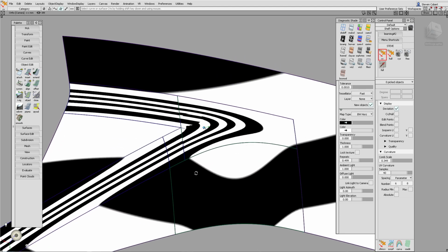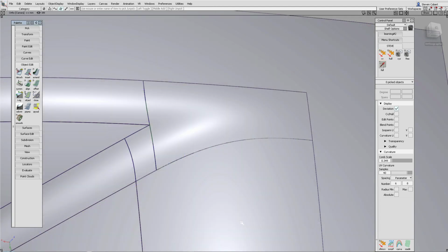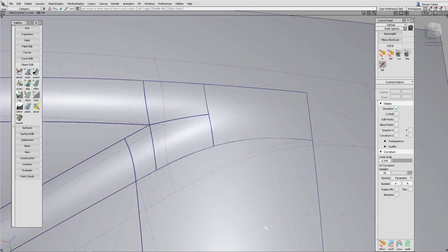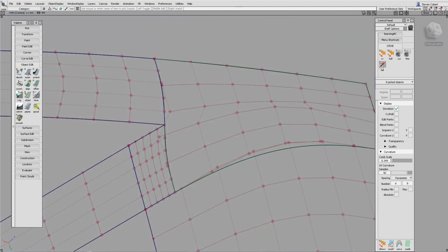The final stage is to split up the surfaces and align them. We need to divide the surface into 3. Where we divide them is a matter of judgment. We don't want the first divide to be too close to the fillet ends, otherwise there's a risk of wobbly surfaces when we come to align them. For now I'm just going to detach the surface at some point, keep the original, and then template this to get it out of the way.